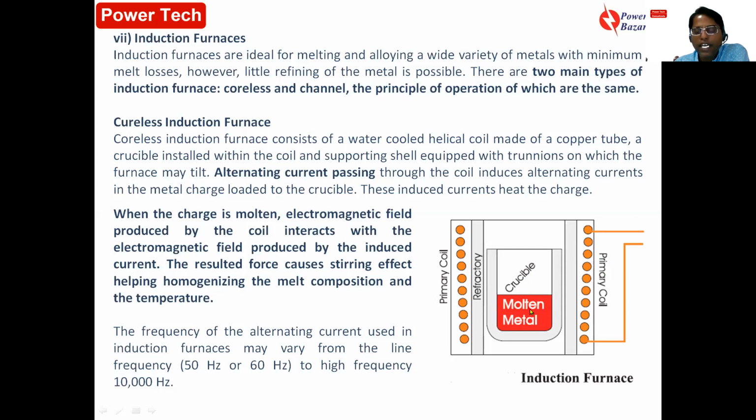Like in induction motors, the motor rotor tries to catch the MMF or the magnetic field of the primary supply, due to which the motor rotates. Similarly, some stirring also happens, which makes uniformity in temperature and material composition. But mainly due to the induction effect, the charge is heated up and gets melted. Normally, the frequency is 10,000 hertz or 10 kilohertz. So this is basically a coreless induction furnace.